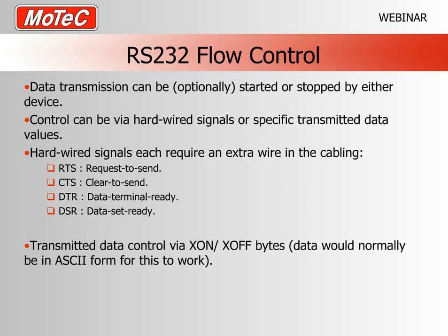Now the reason we have these extra control lines, which are optional, is that we can start or stop data transmission. There are a number of forms in which this can be done. The reason for this, again, is historic, if you like. It's based on the ability of the receive devices to buffer the data. So older IBM PCs, for example, had very small data buffers, and if too much data was transmitted, the receiving device basically couldn't keep up with the amount of data.